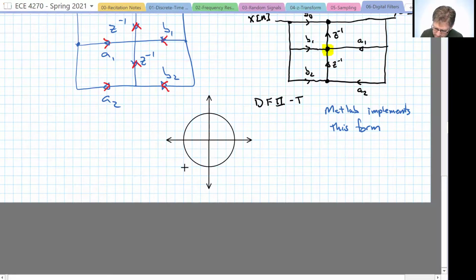And we put in our unit circle. There we go. If we had a pole there and a pole there, that's going to cause our signal to be amplified tremendously by those two poles. But if we're doing a notch filter, we would have a 0 there and a 0 there, at which point we would try to bring it back down. By doing the 0 first, then it prevents overflow from occurring in your filter. So this is just a minor implementation tweak that actually has some big impact in actual systems.